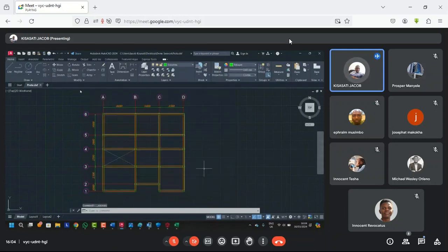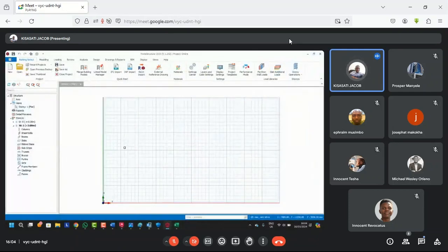How do we bring the model now, to import the model? To import the model under building setout, please just mark this because I want to be faster. You go here to external reference drawing, this one. You click on it. Then you will add the file from the folder where you have saved it. So I'll just add it from here. Immediately it will take you outside to go and search for that file. It's on the desktop, then prota.